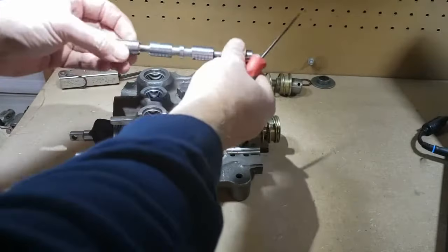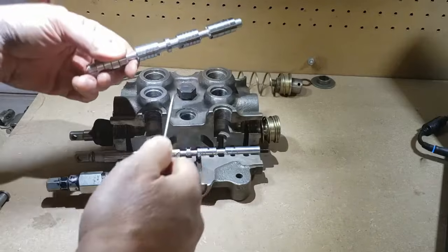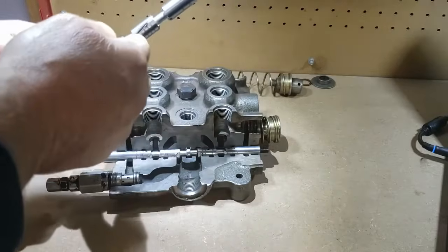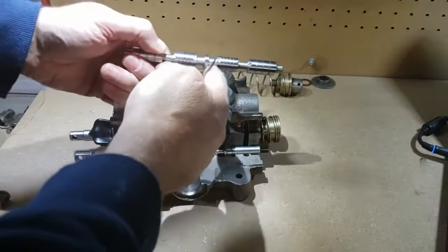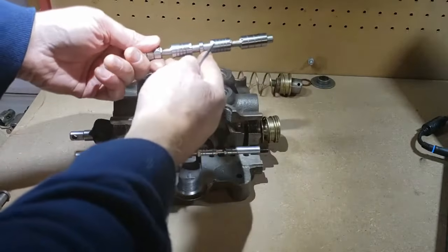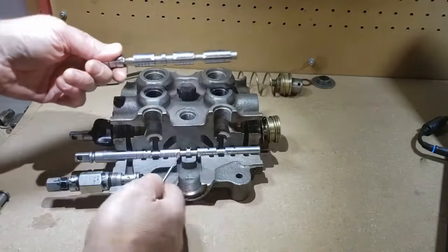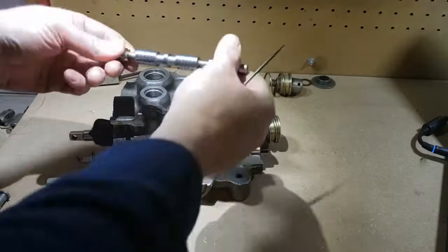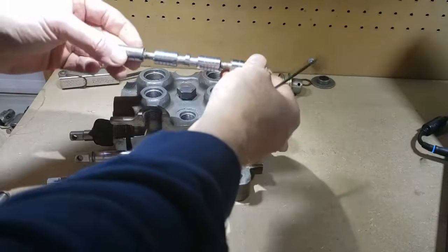And we should review that all of these spools have oil grooves to retain some oil and keep the spool from sticking and sort of lubricate that spool because it has fairly close tolerances. And then there's throttling slots or metering notches engineered in here as well that make that transition from open to close smoother so you can have fine control and fine manipulation of the implements on all 3 functions.